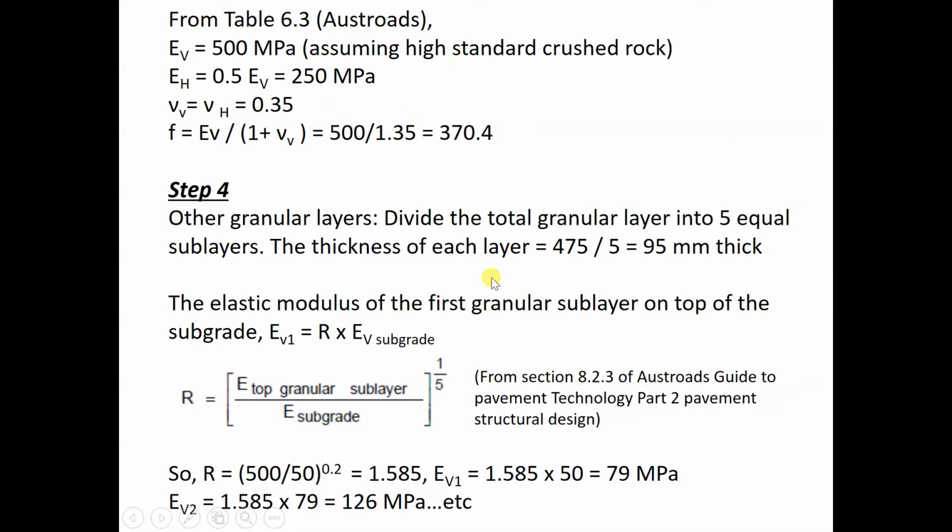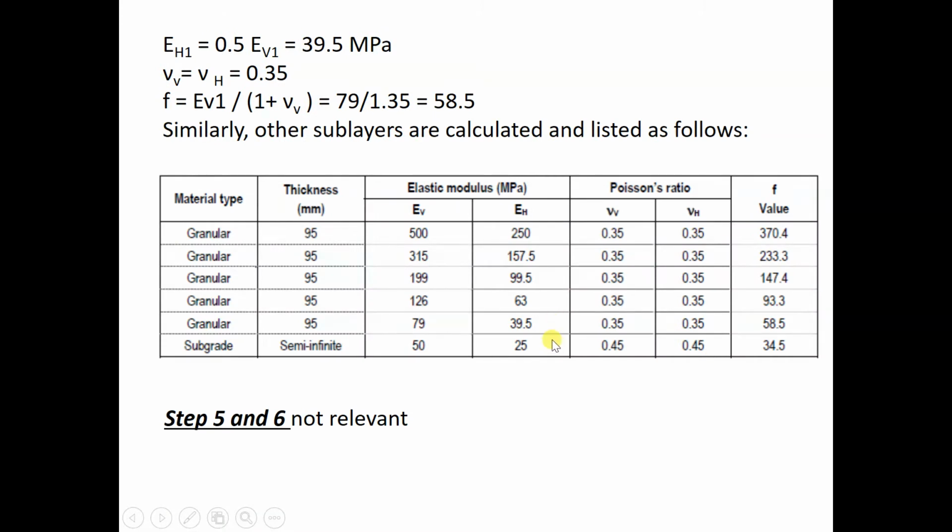I'm not going to go into too much detail, so I just skip the material part, because in the software we just choose a certain type of material, and then the modulus and Poisson's ratio are listed. Then we just select the material and all the material characteristics will be input.